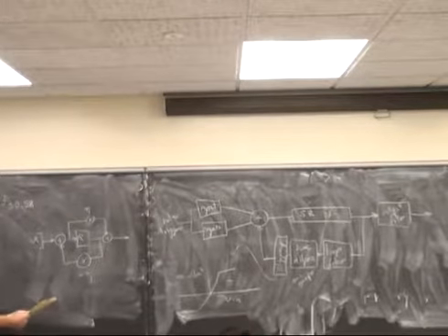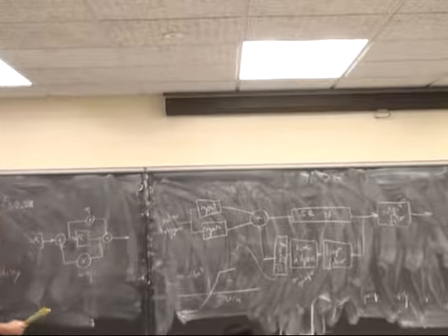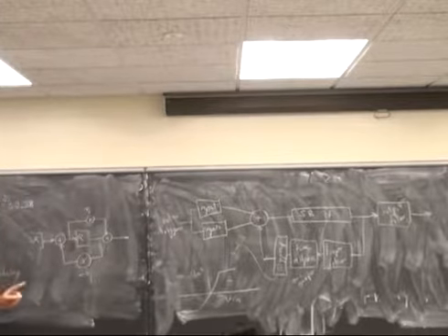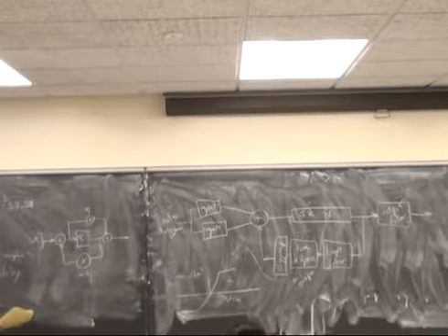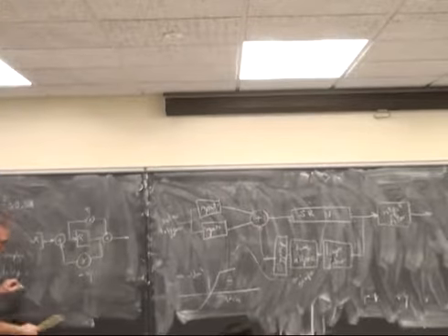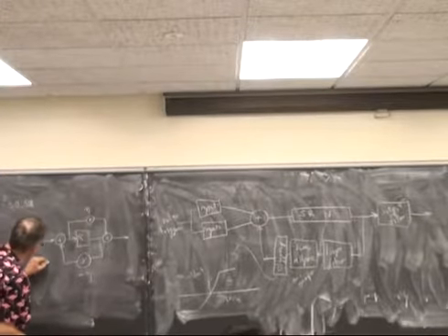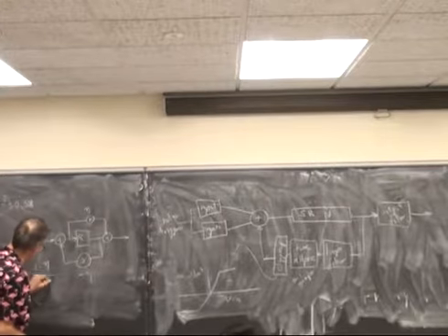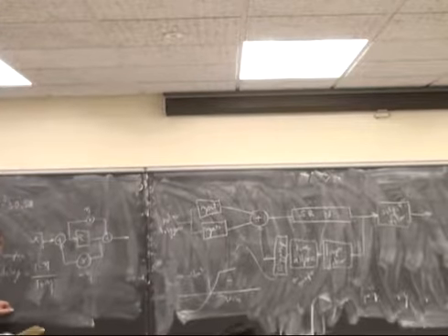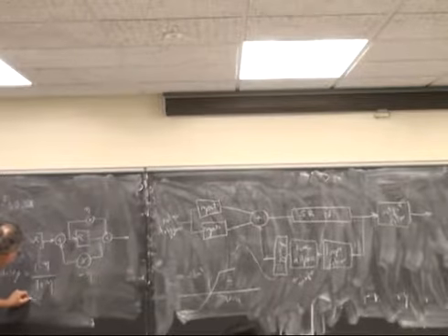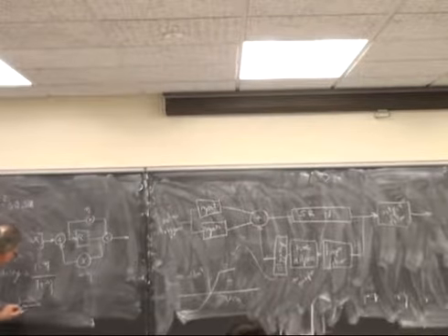And the delay in samples, this is not in hertz, it's in samples, is given by 1 minus eta over 1 plus eta. Or eta is equal to 1 minus delta, the delay, over 1 plus delta.